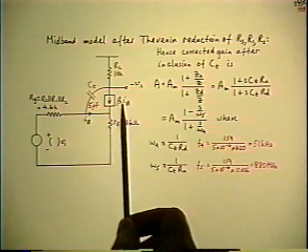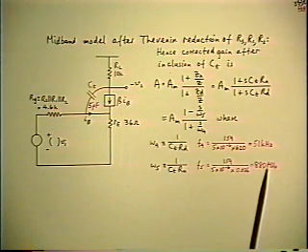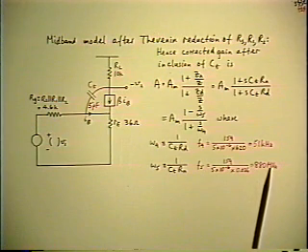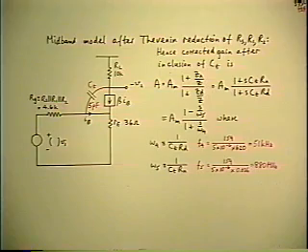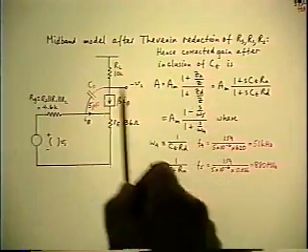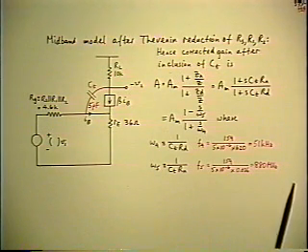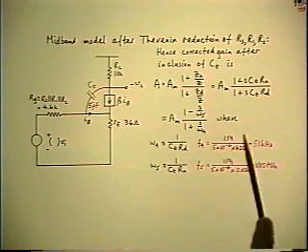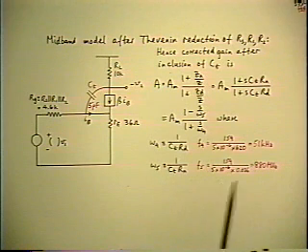Especially when you remember that the phase contribution of the right half plane zero is going to come in even an order of magnitude below where the corner itself is. And then maybe you're going to put feedback around one or more of these stages, where the phase angle of your loop gain becomes very important in determining stability. So you see there's all sorts of multipliers that may cause this effect to be more significant.